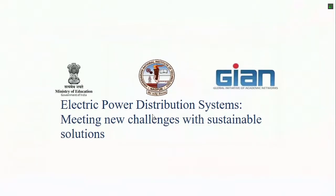Problem at all. The topic of the first lecture is divided in two parts. The first part is more theoretical and we can say academic, the classical problem of reconfiguration of the distribution network, so the topology that can be changed in order to adapt for the operation in the network, or also needs to be changed because something was faulted. So we have a fault in the network, so we need to reconfigure, to readjust the topology of the network in order to maintain the service as much as possible for all the users.